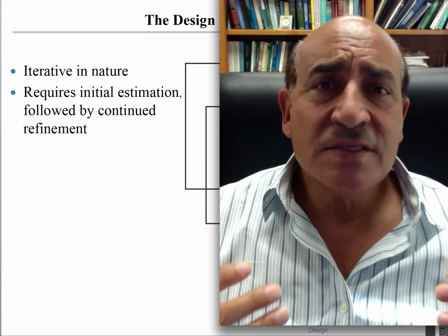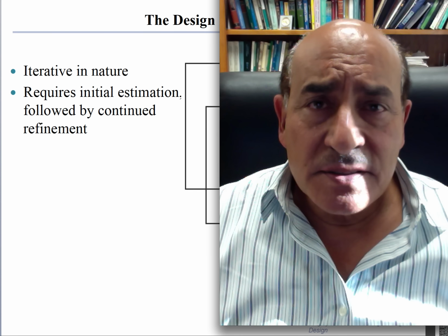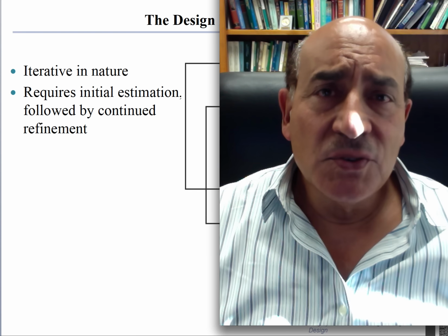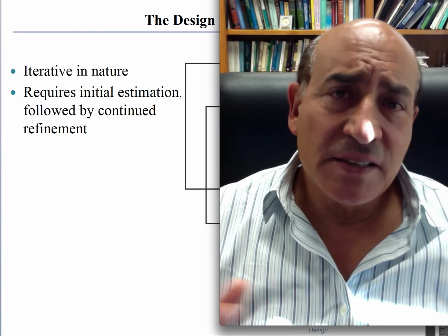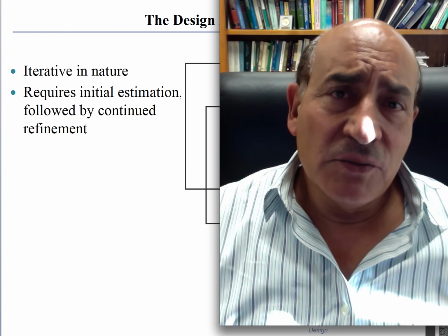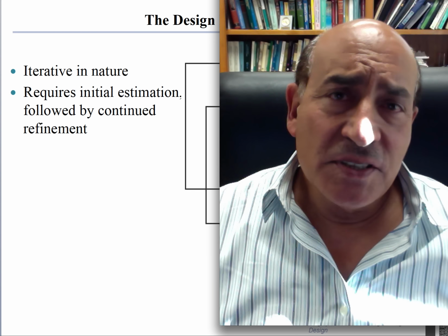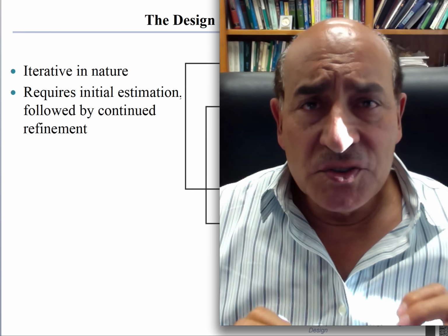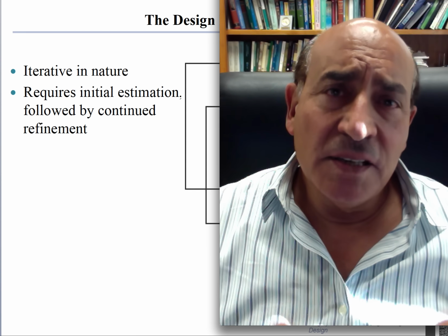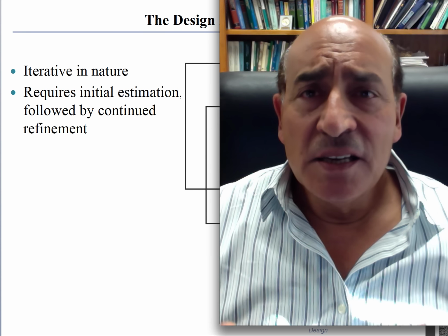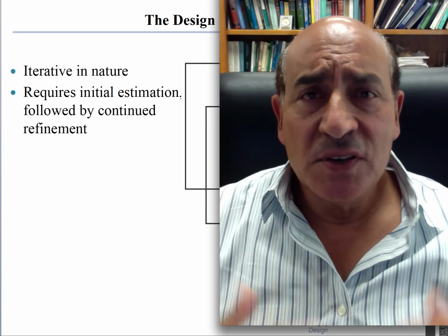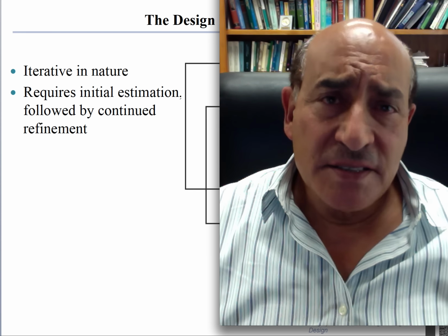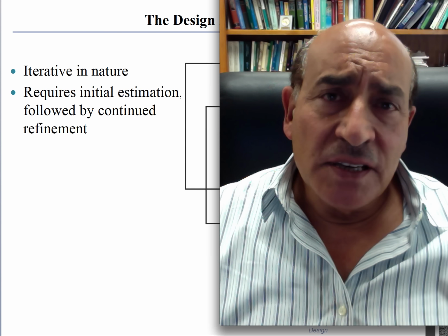What's next? Next is to do analysis. So analysis requires a lot of tools, mathematical tools, mechanics, and so on. And then after the step, I can do iterations, and then I go into the next step, which is synthesis. So I go to every little piece, and I go into detail of how to design each gear, each retaining ring, each key, each ball bearing, and so on. So that's synthesis. Sometimes I cannot meet the design requirements, and I have to do more iterations until I reach the final solution.